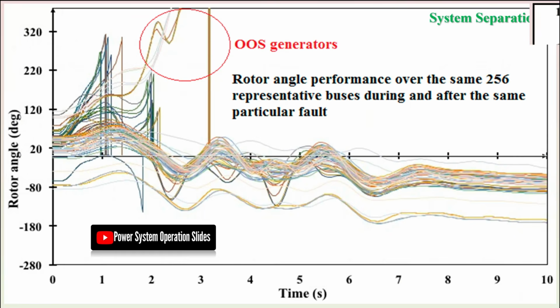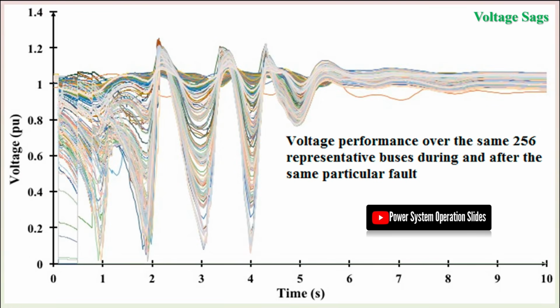The power angle is particularly critical for assessing the overall stability of the entire system, determining whether the grid can ride through disturbances such as generator trips, line outages, or sudden load changes. Phase angle monitoring is essential for managing power factor locally, which in turn involves optimizing reactive power compensation to improve efficiency and reduce losses. The torque load angle is vital for maintaining the stability of individual generators and large motors, preventing loss of synchronism that could cascade into system-wide failures.